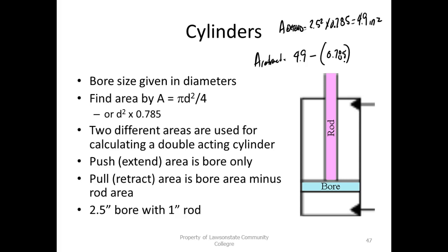So my retract area is going to go down, which means my retract force is going to be, and we can go watch this, by the way. If we take the flow control out, we can watch it retract faster than it extends. I don't think we got any flow control on the one we'll look at across the road. So what's our retract area?